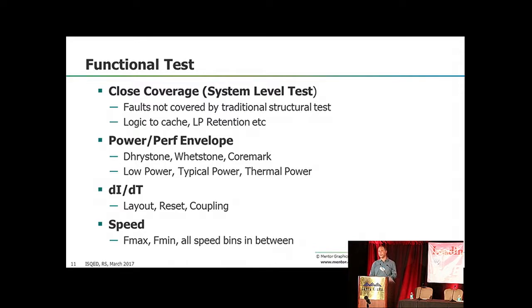It's also used to measure power and performance. So you run your synthetic benchmarks, Dhrystones, Whetstones, etc. And then you can measure things like, I want to put it into a low power mode, I want to see what the minimum power is. I can run a Dhrystone and measure the power to get a typical power. Most importantly, you want to know what the thermal power is, so you can tell your customers what kind of heat sink and what kind of fan to put on this thing.